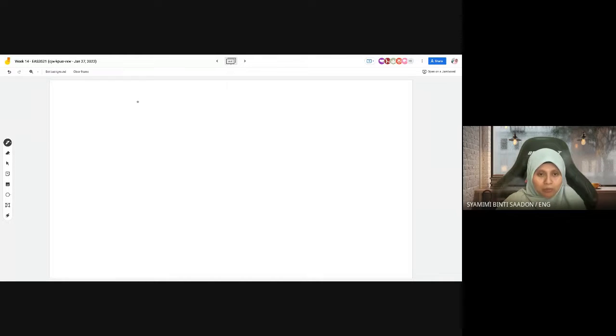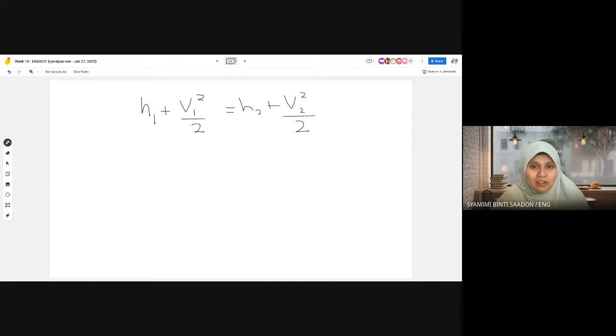So the energy at the input, enthalpy plus kinetic energy, equals the energy at the output. This is from the energy balance, nothing new, except that usually we consider the kinetic energy negligible. But now, since 1 to 2 is a diffuser, we cannot neglect kinetic energy. There is a change in kinetic energy. For a diffuser and a nozzle, we cannot neglect kinetic energy because that is the purpose after all. The purpose is to decelerate and accelerate, so there must be a change in kinetic energy.